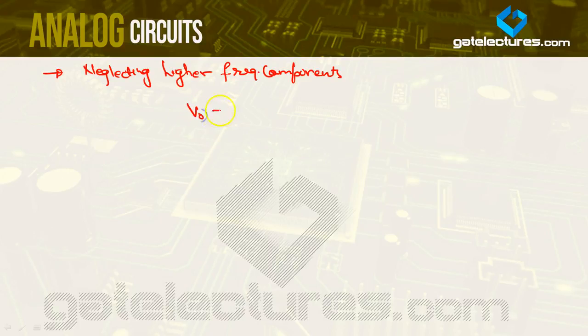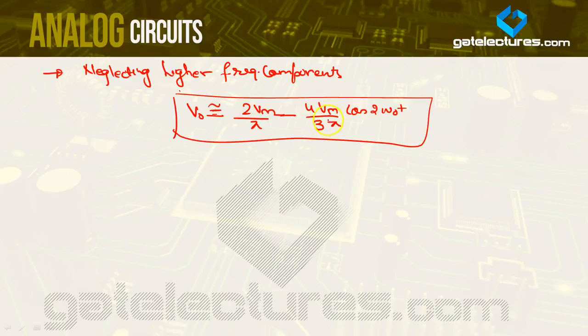So we get V naught as 2 Vm by pi minus 4 Vm upon 3 pi cos 2 omega naught t. We can approximate this thing to this. So we can represent a full wave rectifier with this small circuit without even considering all other parameters. We can just replace it with one DC voltage and one AC voltage, and then we can calculate whatever we want to calculate. This is how it looks: 2 Vm by pi minus 4 Vm upon 3 pi cos 2 omega naught t.